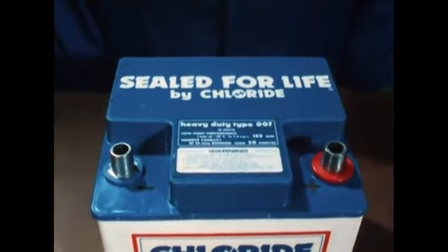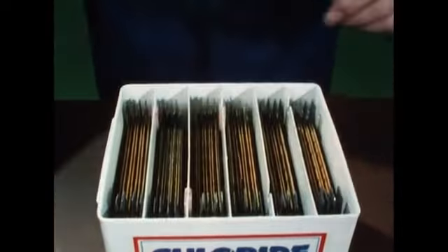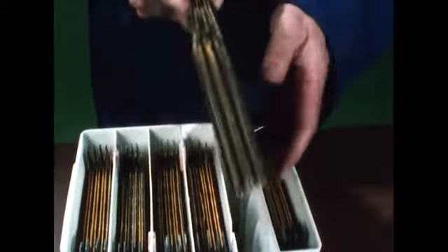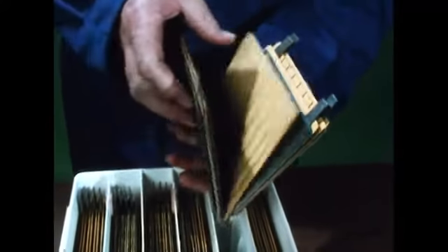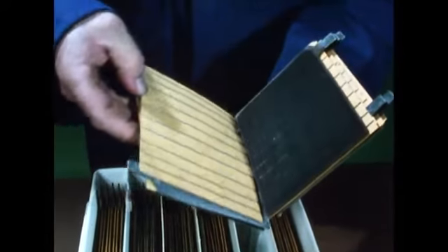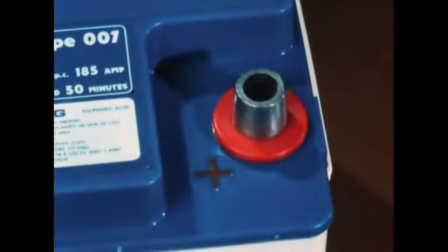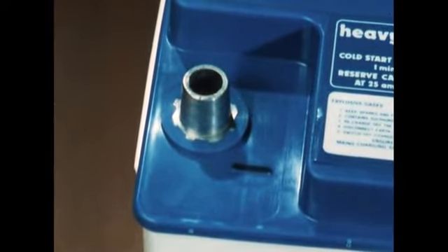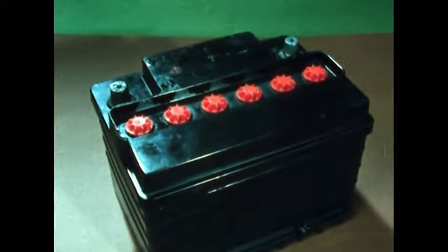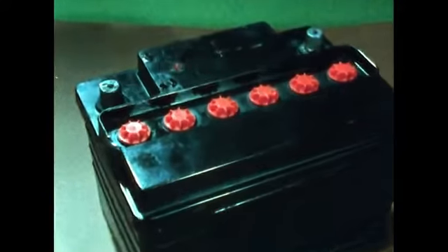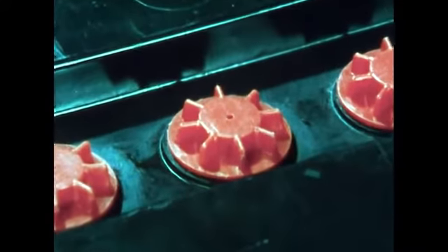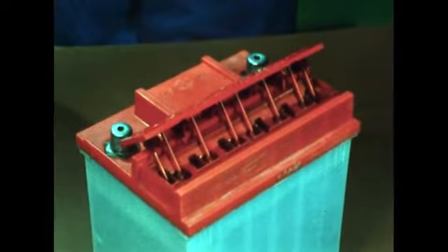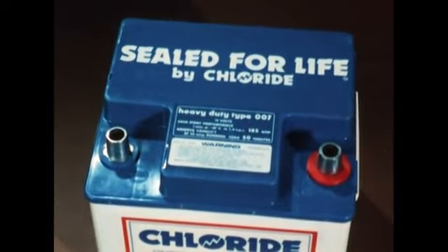In order to get a worthwhile amount of electricity out of a cell, the plate area needs to be as large as possible, so the plates are made with this in mind. Several plates of each sort are connected together, and the interleaved separators make sure they don't touch. Usually the positive and negative terminals are clearly marked. And sometimes there are caps which can be unscrewed for adding distilled water. A vent in each cap allows any gas produced during discharge to escape. Other designs have different water-adding systems. And the most modern batteries never need adding water at all.